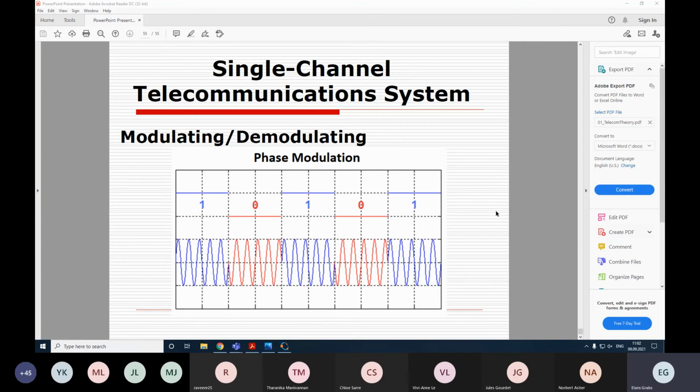And for the phase modulation, we have different initial phase. So here we start as a plus sine. Here we start as a minus sine. And, well, from the school trigonometry formulas, you might remember that sine of A plus pi is actually minus sine A. So we change the phase by pi here, yes? And that's accordingly what makes this modulation type.